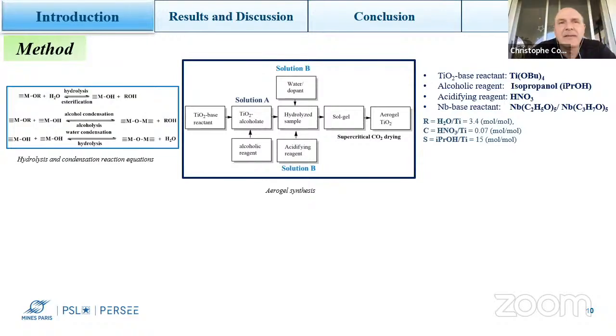No, because I think in this kind of system, when you have your aerogel after your drying, you need a calcination step to crystallize and to burn all organic compounds. But I think between 450 and 550, you have a good window, and sometimes it can be better not to go higher than 550, and you can keep more surface at 400. No, you didn't. You already made your calcination at 550.